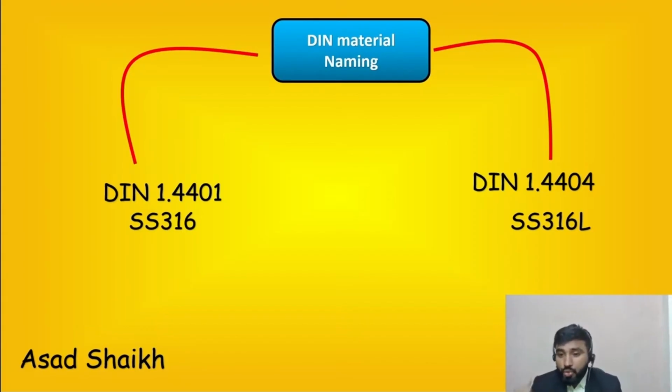So first thing is you should know which kind of material your application requires. And I would like to give you some thumb rule. If your line size is small, vendors can give you a forged version. If your line sizes are too huge, it is difficult for them to give you a forged version. If it is still mentioned in your spec that they want a forged version, then you should definitely raise this, I would say, for leniency when it comes to very large sizes.